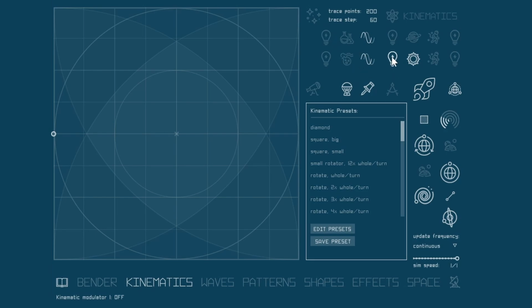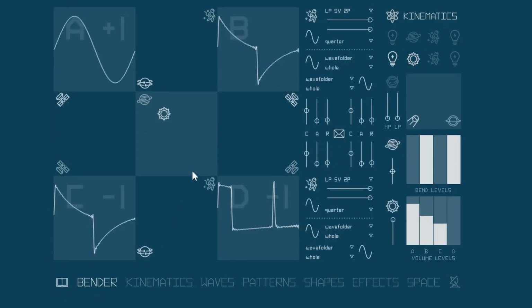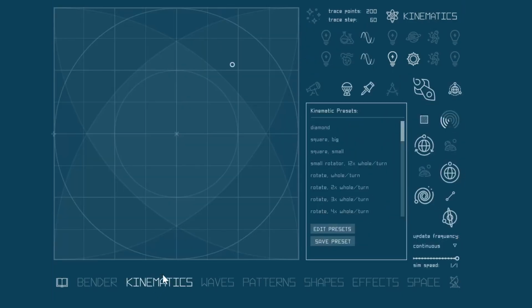And kinematics label switches the whole engine on and off. When the engine is running and a simulation is active, it takes control of attached XY cursor. At this point in main video, I concluded that the whole section is somewhat optional, and you can simply use presets.